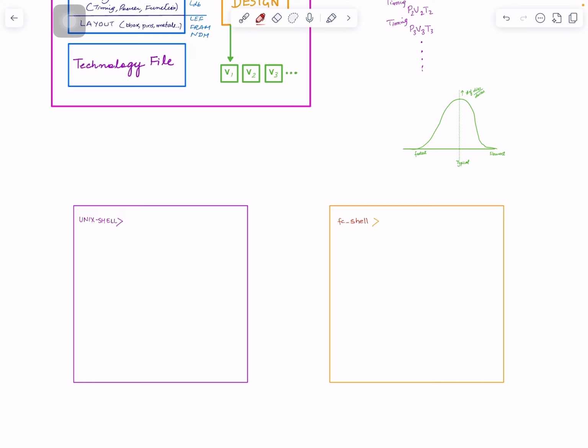You can do that using the echo command on $0. That will tell you which kind of shell, because you might need to do some shell scripting, not for this setup, but eventually, for file reporting, parsing, automating firing of jobs, or automating the start of FC shell or other tool shells you have.